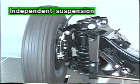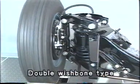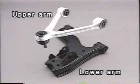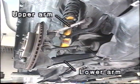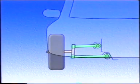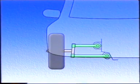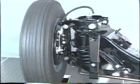Next, let's take a look at independent suspensions. A typical example is the double wishbone type, as explained earlier. A wishbone is the breastbone of a bird. An upper arm and a lower arm resembling this bone support a wheel in the longitudinal and lateral directions. This type is widely used for the front and rear suspensions of front-engine, rear-wheel drive vehicles.